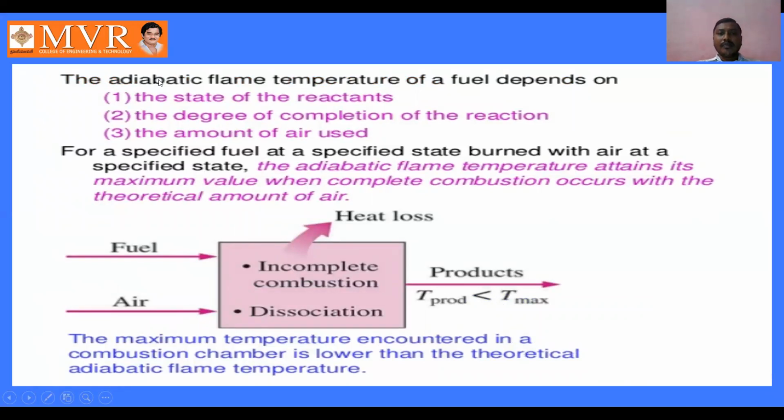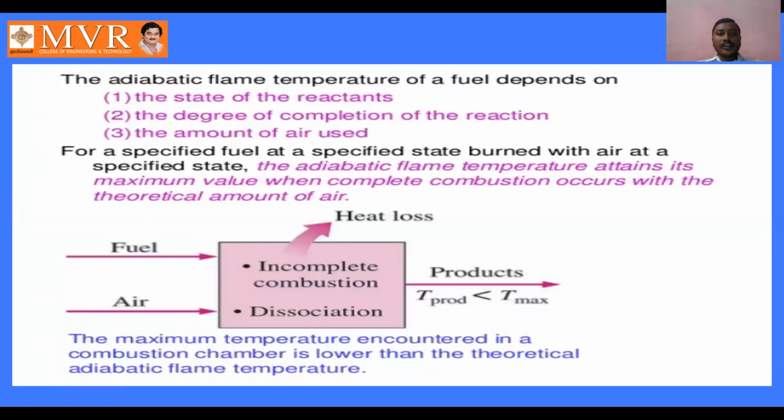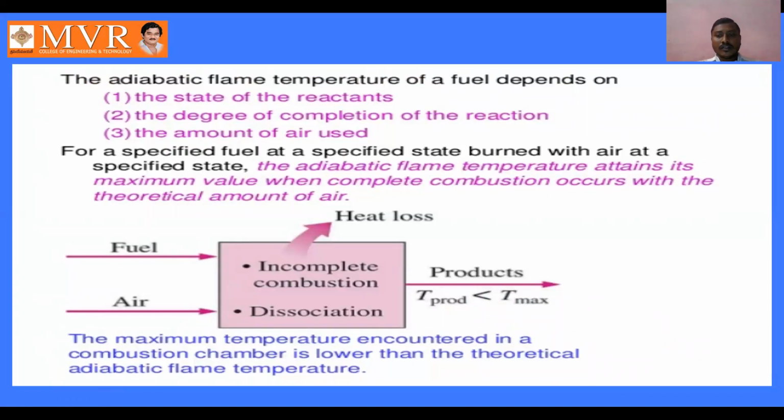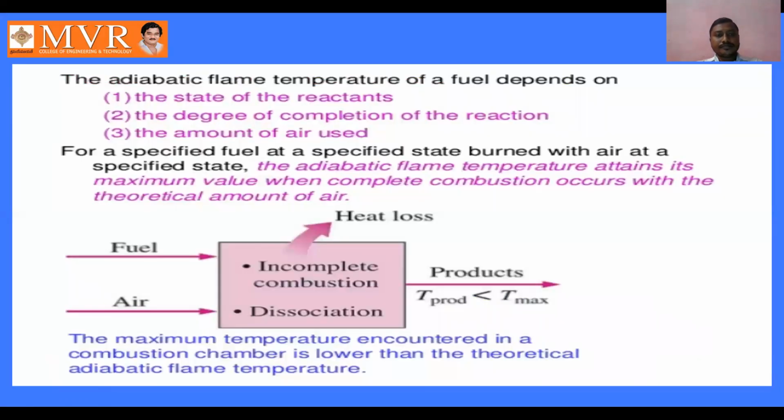The adiabatic flame temperature of a fuel depends upon three things: the state of the reactants, the degree of completion of the reaction, and the amount of air used.